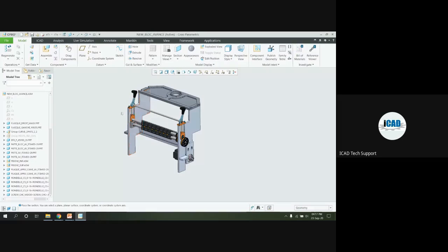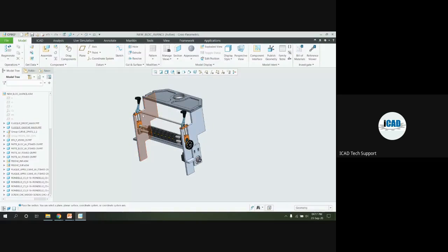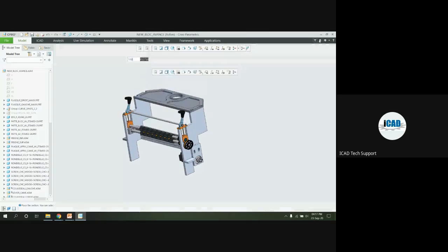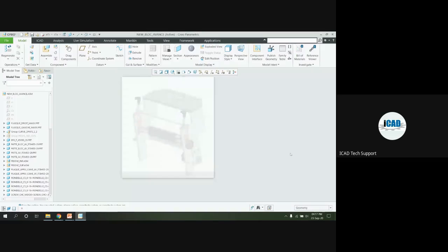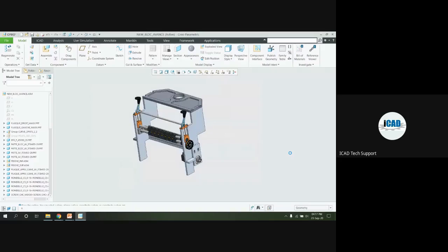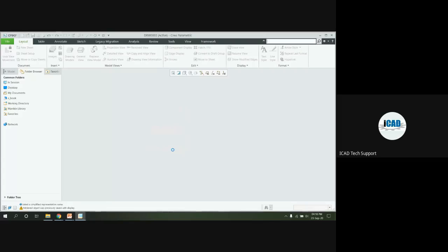So let's move towards the 2D drafting and detailing. For that, in the Creo environment, some shortcuts are available. We can call them map keys, in this search toolbar. You can use these map keys. You can see I have saved multiple map keys. If I want to open a new drawing, I just enter ND on the keyboard, and my assembly drafting window will appear.